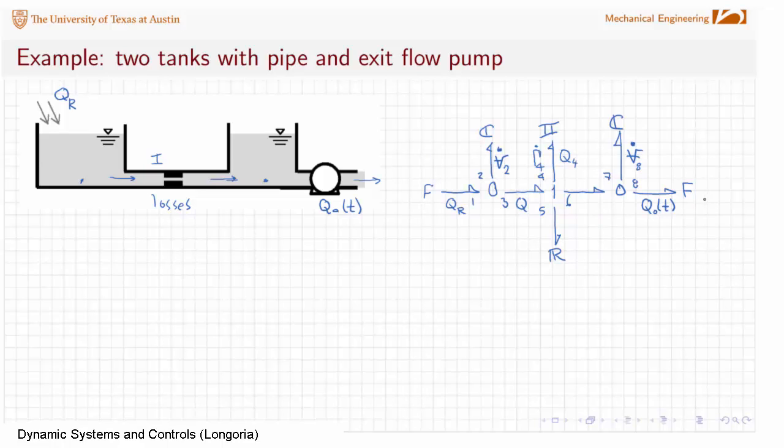Okay, so I have a flow source here and here, and so I have to start with one of these sources. I'm going to go ahead and start off with this one. That has to be a flow in, right? I come in with a flow into a 0 junction, and remember that does not constrain your causal assignments. It doesn't propagate through. A flow into a 0 junction does not mean that you are constrained to assign these in any way. So you have to stop there and look for other sources before you start looking at energy storage elements, because we know we have another source here, so I need to come in and put my causal